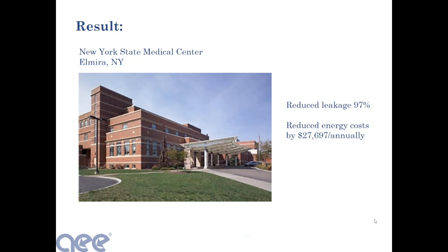We've seen them sag, maybe there's 5 feet of ductwork laying on the floor when there doesn't need to be. Those are the sorts of things that, whenever you bring in an aerosol-based contractor, they should be looking at. They shouldn't just be connecting the tulip, but looking at the entire air distribution system and making those types of recommendations, so when they see pressure drop problems, they get fixed. It's a good question. Other questions?